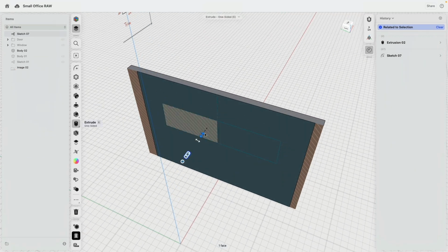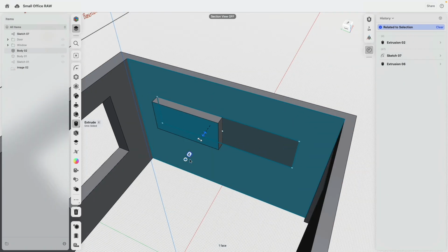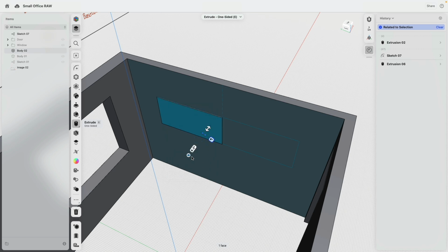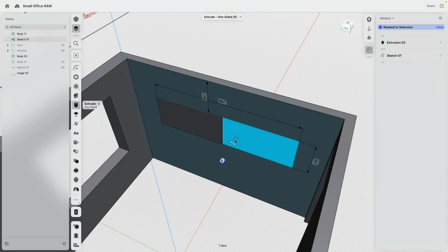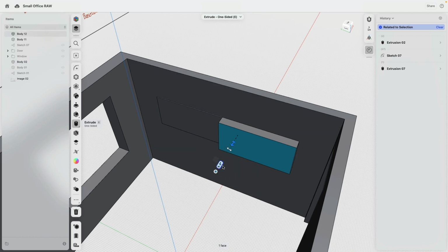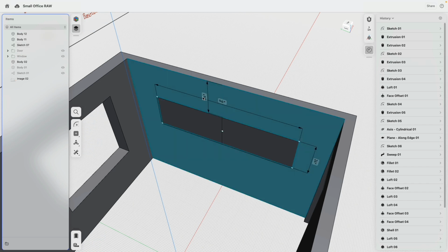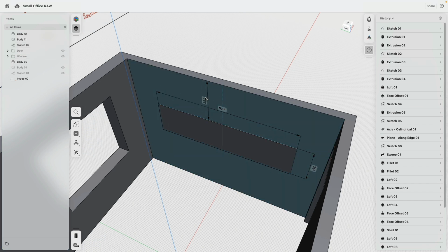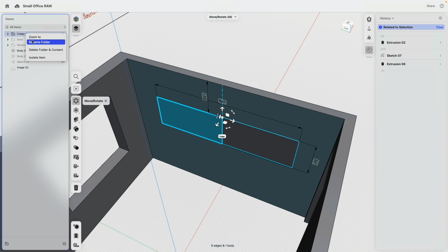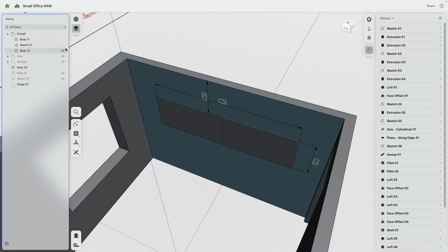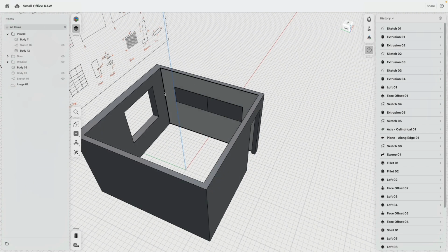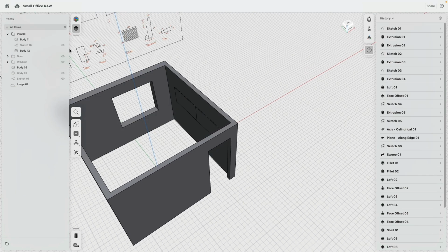Now here we have our panels. Maybe turn section cut off. I'm going with 0.5. So a new body, so they are a tick bigger. Logically, it's way too big, but so we can see those. And here one more time, when we go ahead and change everything there, everything follows. Beautiful. Cool. Yeah, there is our pin wall. Now you see, step by step, I worked on all these walls.